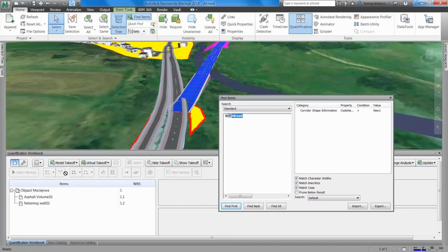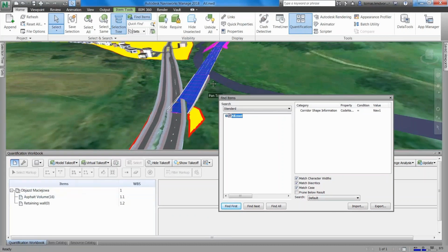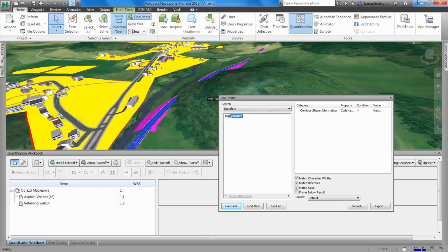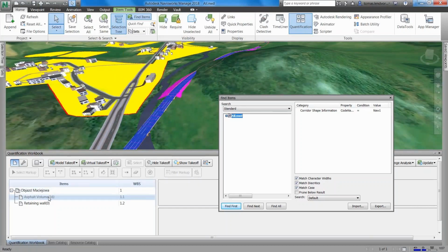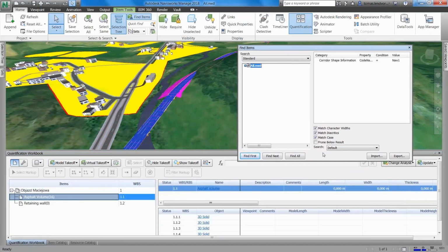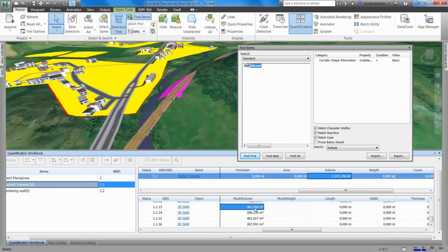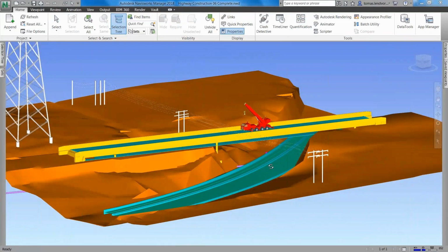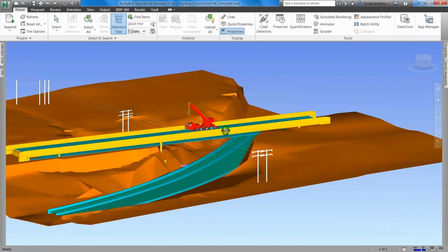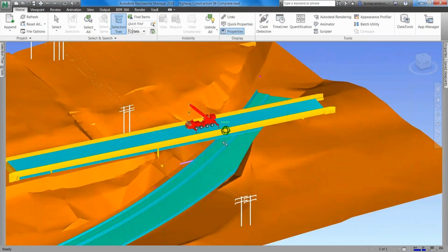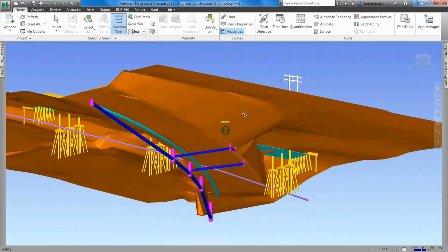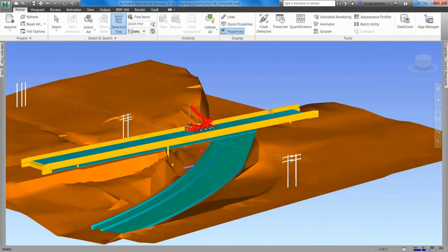So now I have all this information. But obviously what I can do is filter it, or, okay, maybe the first 500 meters. All this can be done, and I can interrogate what, for example, the asphalt volumes are. And I have it. The system will not only find it, but will also calculate it for me. So I have a volumetric calculation for each piece of asphalt, how it has been designed, but also the entire volume.